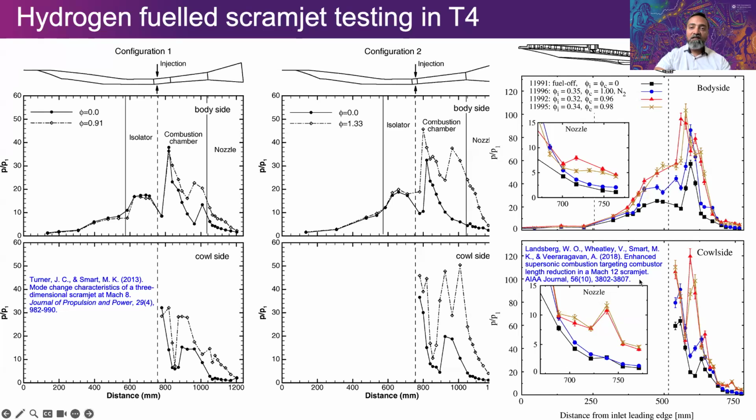Mach 12 is a very high speed, and even with hydrogen fuel, which burns nicely, it's difficult to burn. So we had to inject fuel at the inlet, which is something we, like I said, embrace and take advantage of, mixing the fuel from a far upstream location, so that by the time it comes to the combustor, there's already some pre-mixing potential for ignition, and then we inject a lot of fuel here. So this shows you the split between the inlet and the combustor injection of fuel. Again, here there are 4 different curves. Again, normalized plots in pressure, unfueled, a combustion suppressed case, which was our first sort of proof to answer that question. How do you know you're actually burning, supersonic combustion?